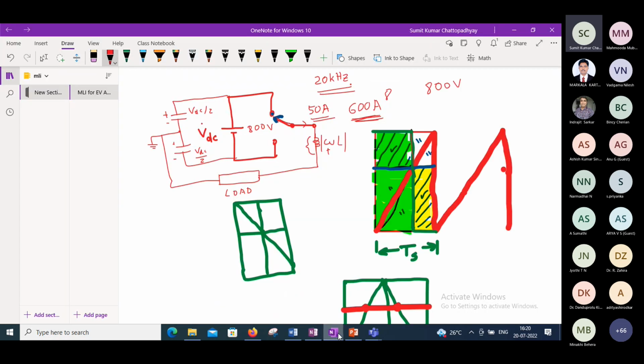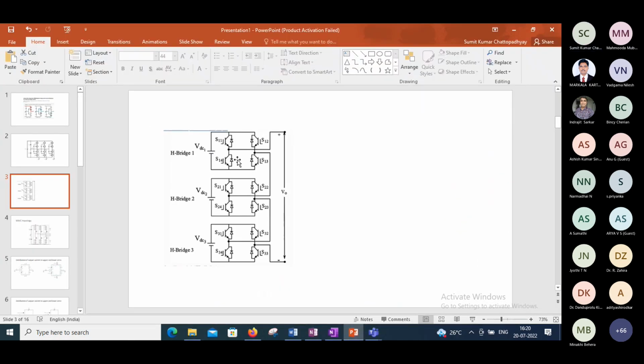And that finally gives this concept, the cascaded H-bridge, that can bring modularity, and these bridges can be realized with MOSFETs. And not only that, when we break this into multiple parts, it can also, up to some extent, offer active battery balancing without additional circuitry.